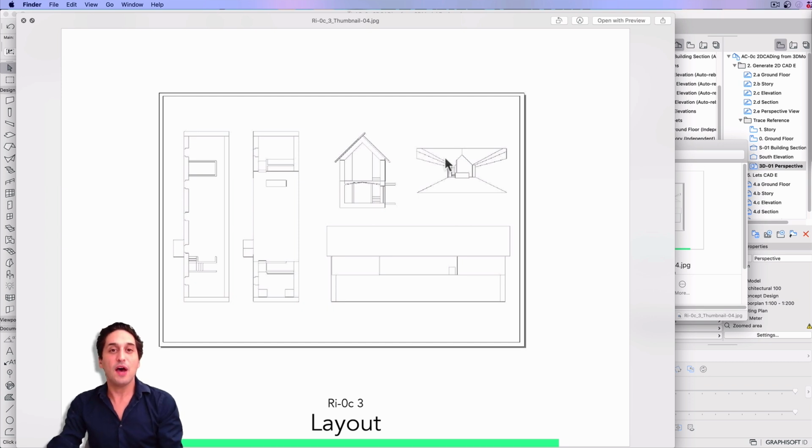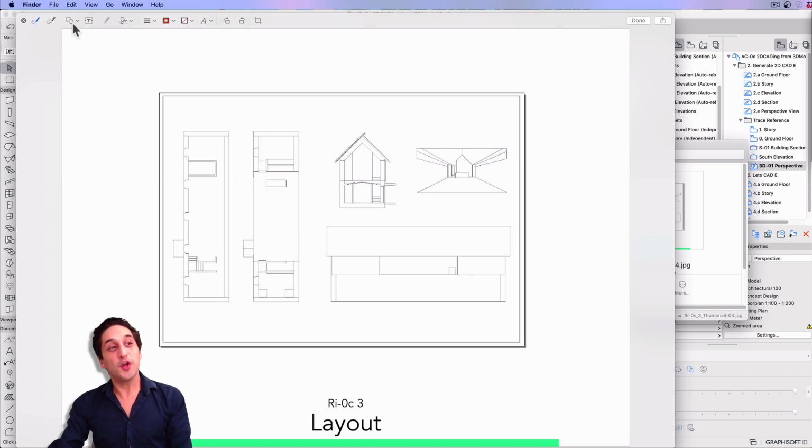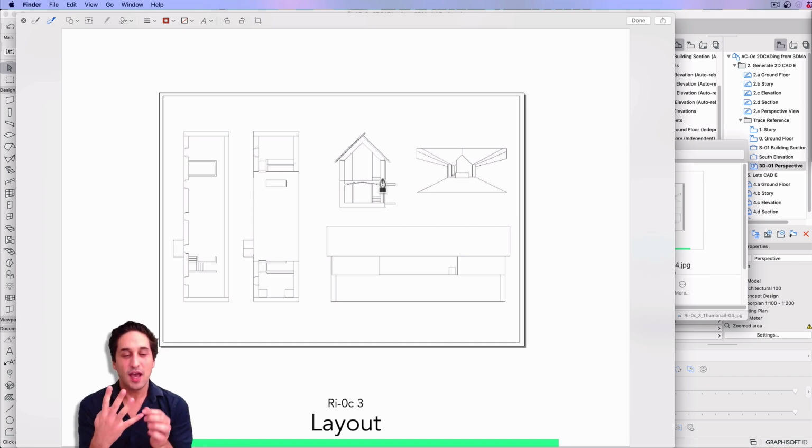All right, so after that, you should print that out on paper. All right, I'm not joking here. You have to print it out on paper and start thinking about which lines should be thick and which lines should be thin. Now, you will understand that in my course, everything can be done with 4 pens. A very thin pen, the next one, and then a little bit thicker, and then really thick. At the end, we name them 1, 2, 3, 4.